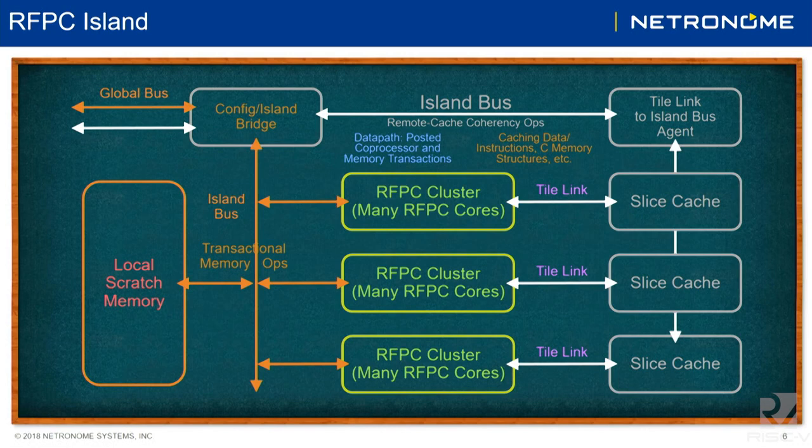The other types of operations that are required, we mentioned, are transactional memory operations coming out of the left-hand side of the block diagram here. Those also use the load store instruction set from the clusters, but they form operations that get executed elsewhere, as close as possible to the memory. And then there is an operation that allows the waking up of the RISC-V processor.